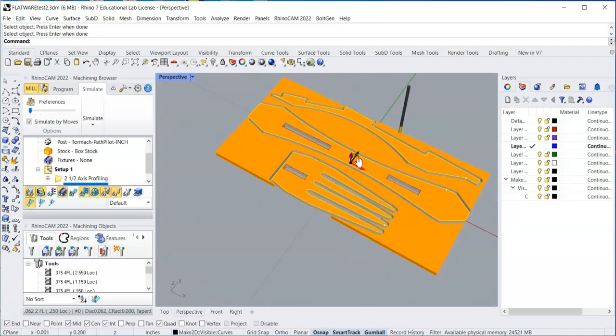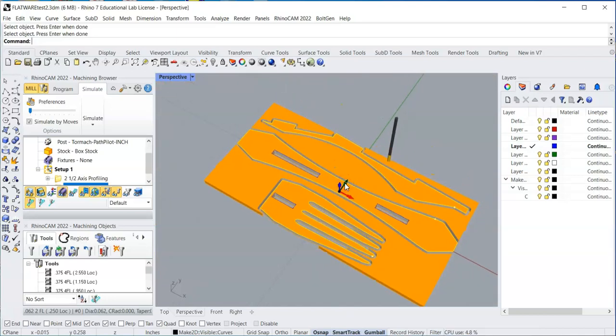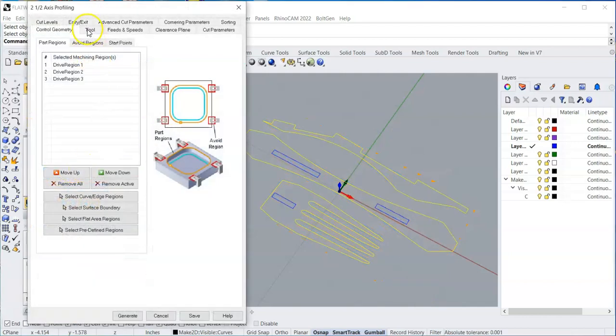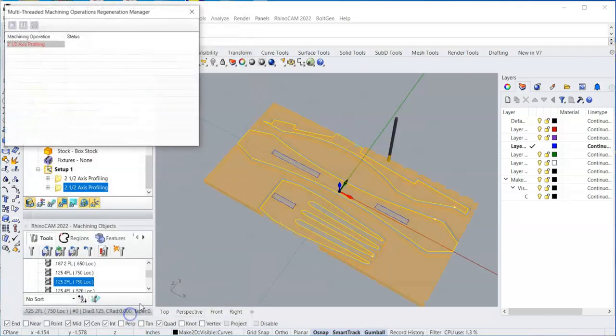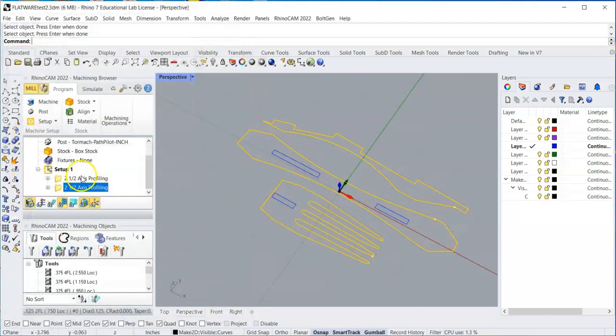All right, now, what's the problem with cutting clear through those pieces? Yeah, they're going to fly out of there, and they're going to get nicked by the bit, and it's going to fling it out and smash your face, right? So we've got to figure out a way to control that. We didn't have that problem on the first one. Now the other thing we can do is speed this up by using a slightly larger tool, right? Instead of using that little teeny tiny 1/16 inch end mill, we could go back to our other end mill. We just have to change out our end mill in between, right?